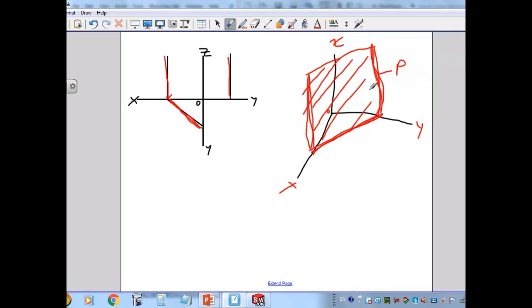So this is called the horizontal projection plane, because this one is the horizontal plane, right? So the H plane has a kind of slope. It's not parallel, and it's not perpendicular to this horizontal plane. So it's making a trace. The trace is not parallel and not perpendicular in this xy plane, or horizontal plane. So that's why we call this one the horizontal projection plane.